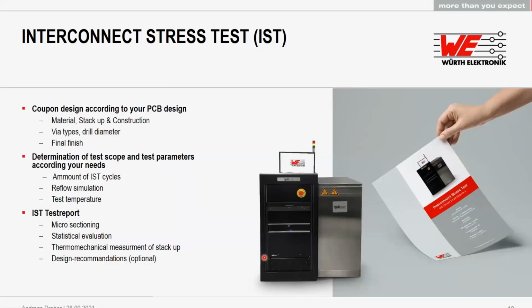These tests were done with an interconnect stress test system. So we have these test machines dedicated for testing. You can use coupons put in the board, and they are heated up from room temperature to your test temperature. A typical value is 150 degrees, but even more is possible. And also a major influence is the reflow simulation.